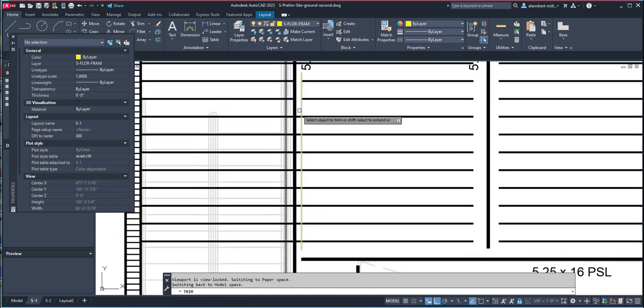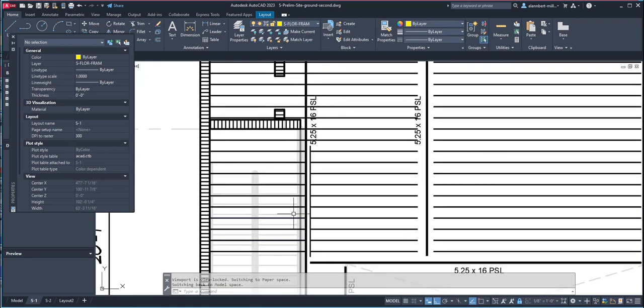And let's do a fence. F for fence, so we can select objects by a fence. If you didn't learn that in, what, 310? Is it 310? For your AutoCAD class, you can always select objects by trimming them with a fence. Okay, and I can just erase all these lines that I wouldn't need.